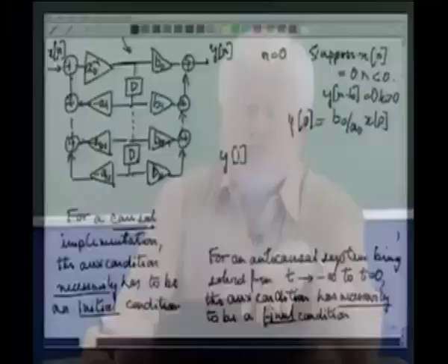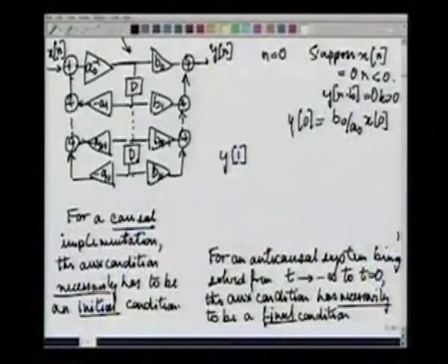That is, at n equal to 0, this was x 0 divided by a 0, not b 0, y 0, x 0 by a naught. X 0 by a naught is now available at this point. It is the quantity that gets multiplied by b 1 on one side and by minus a 1 on the other side, and gets added to x 1.